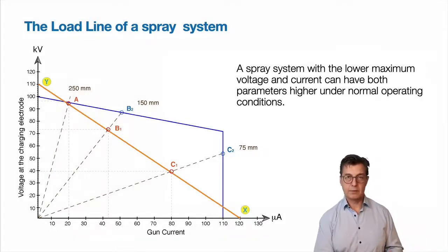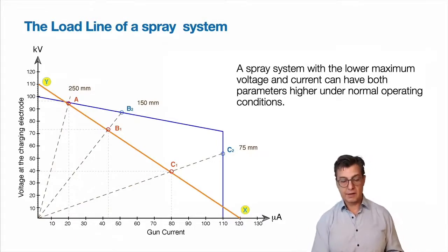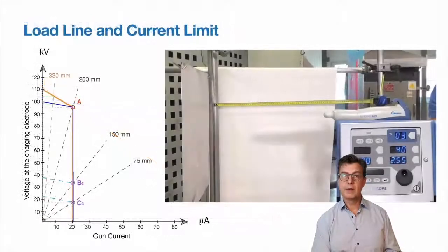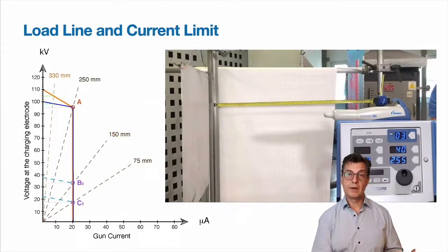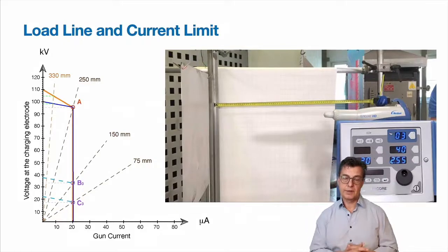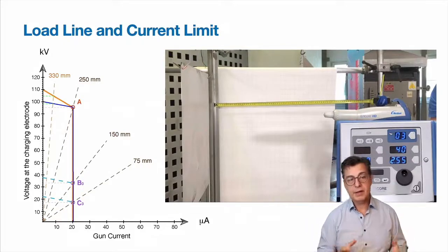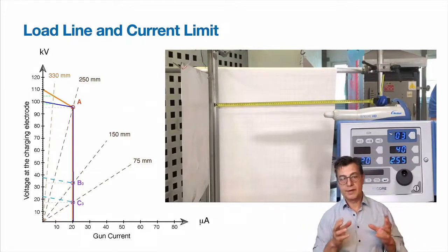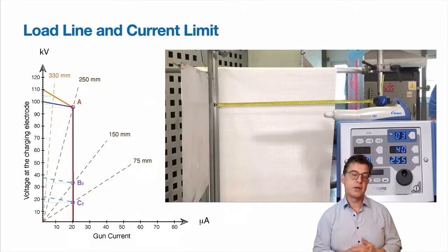Does it mean it will be better? Not necessarily, because higher voltage can also translate, and it does translate, to higher current, which in many situations can be excessive and lead to back ionization. So what's the solution then? The solution is to control current. To delay back ionization, we must control and optimize, not maximize the charge.